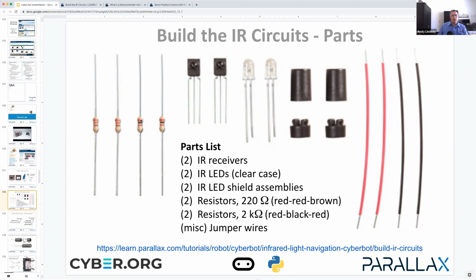That was with the whiskers. These are smaller resistors. They're red, black, red. Your robot will be too nearsighted if you try to use the 10 kilo ohm. These are about a fifth of the size. They resist electric current flow by a fifth of what those 10 kilo ohm resistors you used during the whisker activity did. Okay, thank you. Certainly. Thank you for asking.